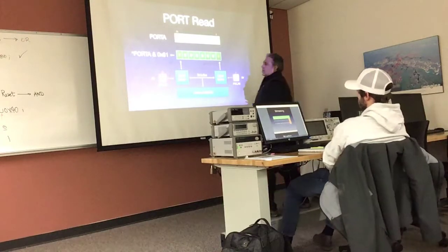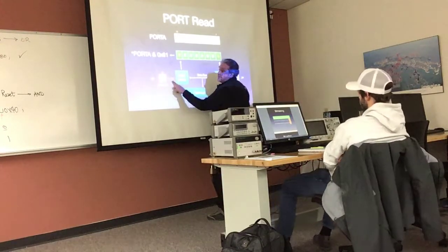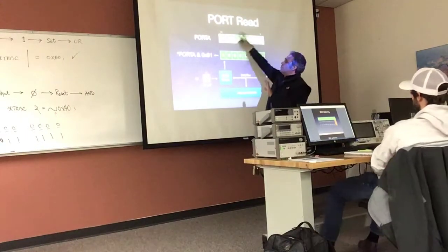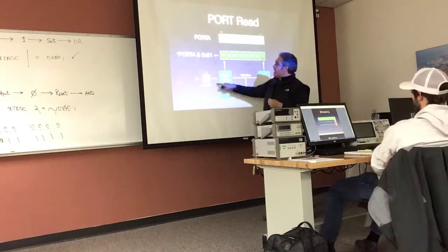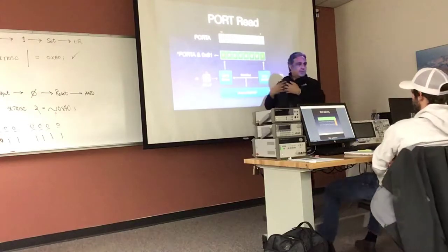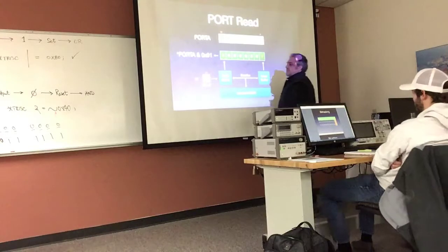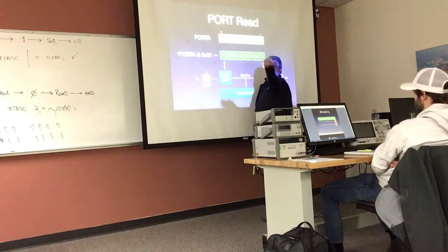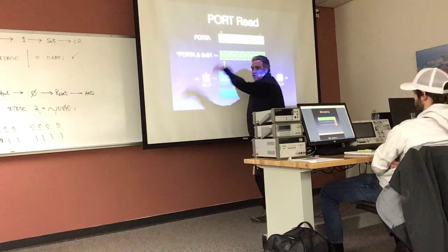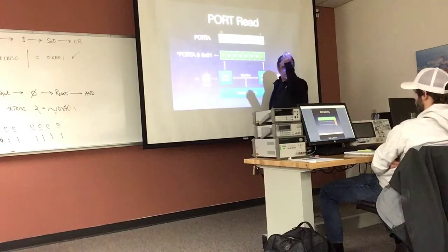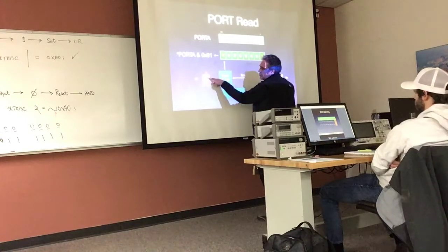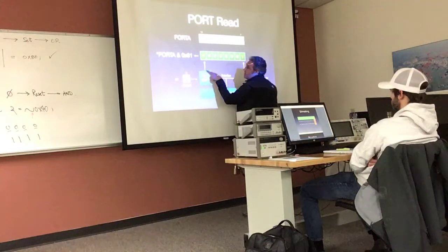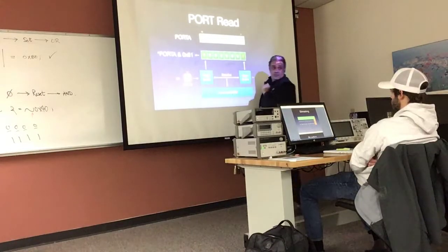But look at the arrow. The arrow means an input. That arrow is telling me that before I was capable of doing any of this, somebody set my pin A7 as an input. So if you physically put a grounded pin on pin A7, I mean I take a piece of wire, I hook it to 13, and I ground that pin, like you physically ground it, that will put 0 volts on pin 13. The input buffer will pass that data up into port A, the register.